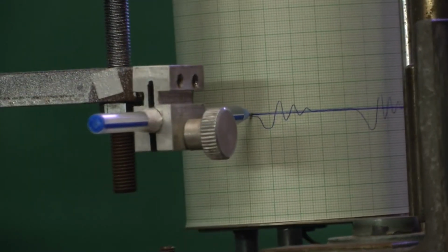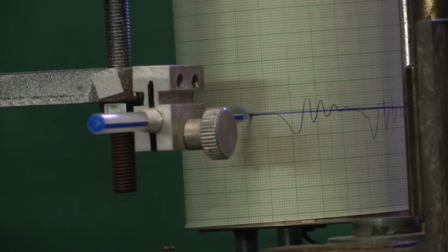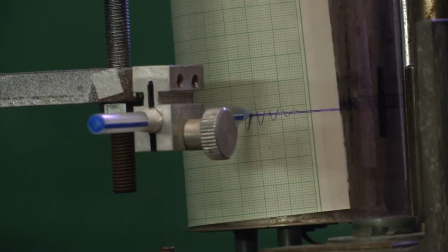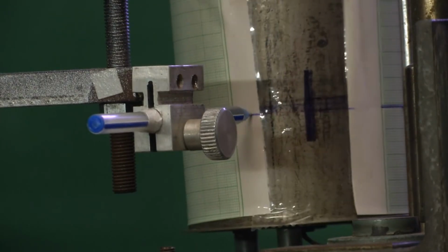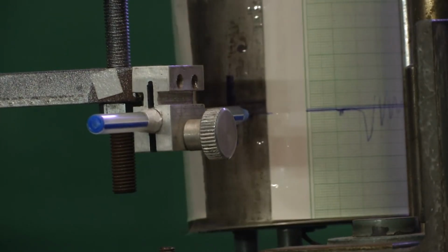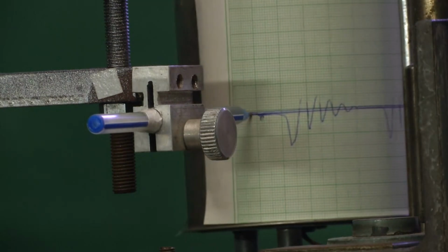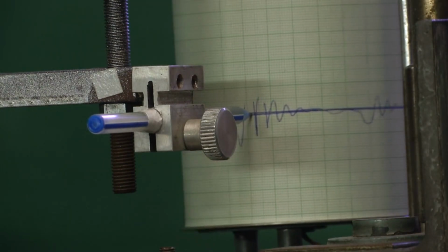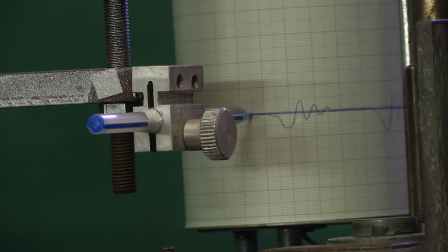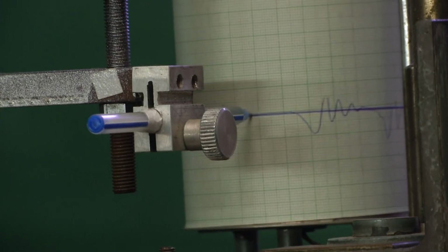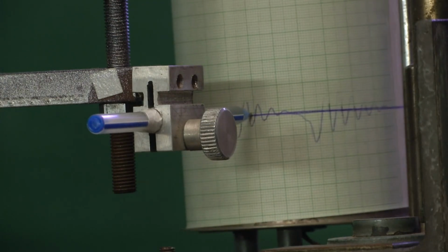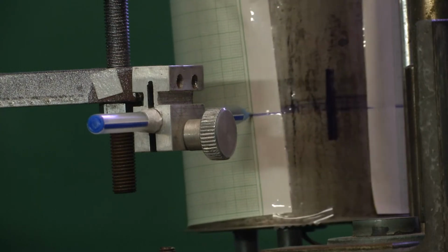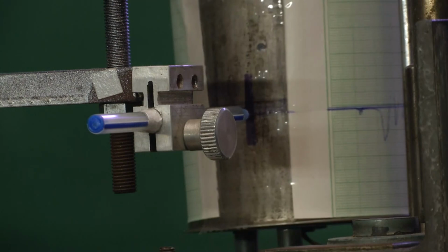Okay, so this is how we get the time displacement plot for the case when the dashpot is connected in the system. So, what you have observed is there is quite a heavy damping in the system, that is why within a few cycles the amplitudes are coming back to 0, and the decay is faster, and that is why the logarithmic decrement will be a larger value in this case.